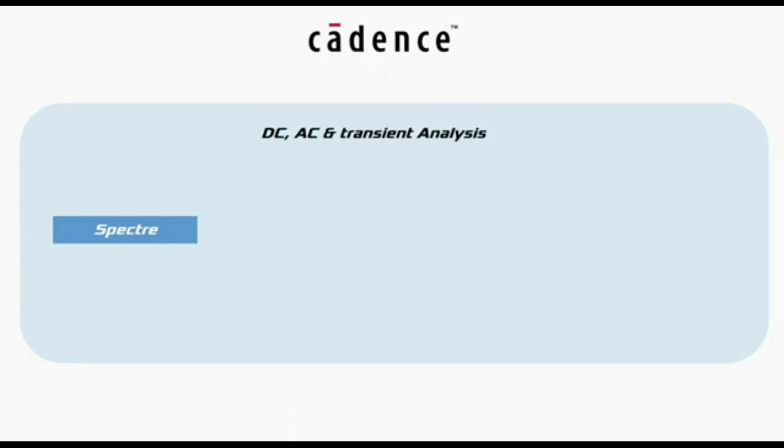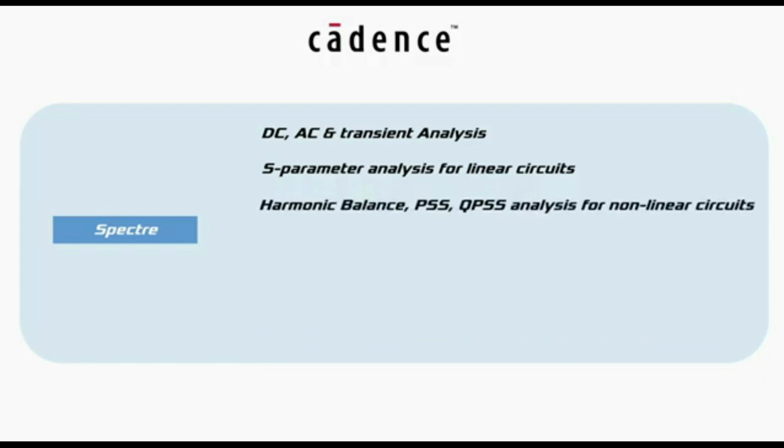It provides a bunch of powerful analysis tools such as DC, AC, and transient analysis, S-parameter analysis for linear circuits, harmonic balance, PSS meaning periodic steady state, or QPSS, quasi-periodic steady state analysis for non-linear circuits, and many more.